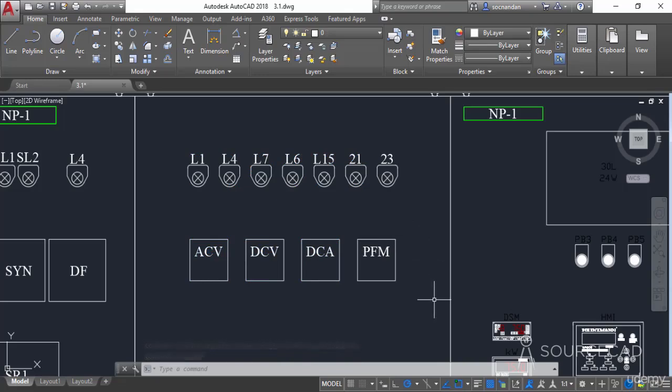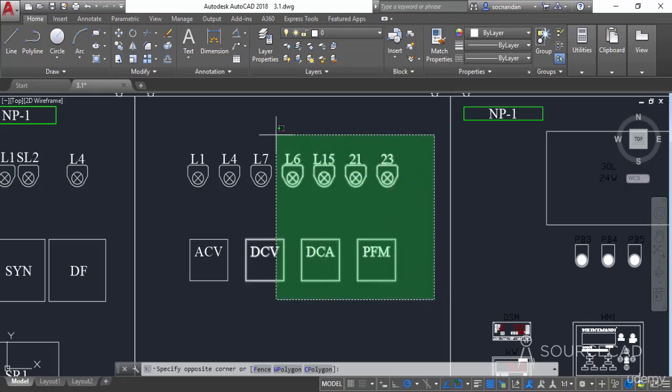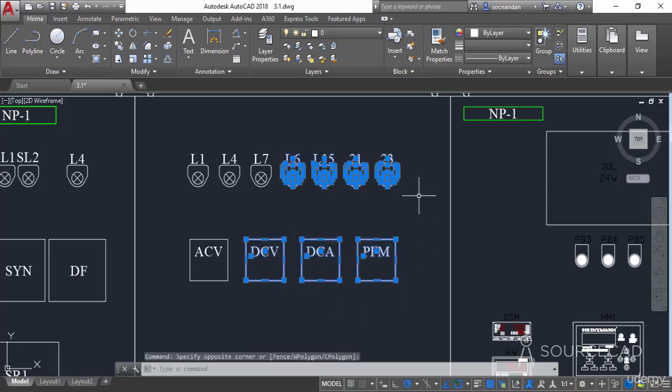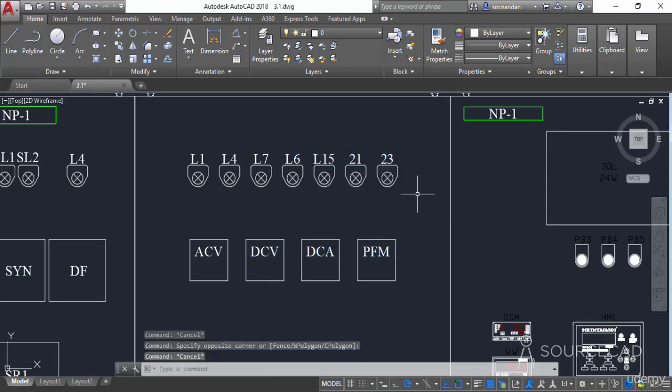Now let's repeat the process with another window. I'll click on the right side of the drawing area and move my cursor towards the left, and now we have this dashed window. In this case, everything which is completely inside this window is obviously selected, but also the objects which are touching this window are selected. This rectangle and the text here are also included in the selection set, although they are partially inside and partially outside, because they are touching the window. So this is the second way of selecting objects. You can use either of these options, and we have many other options also for making selection.